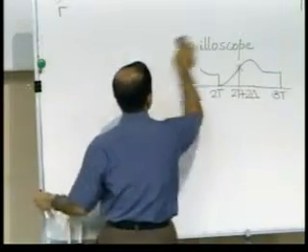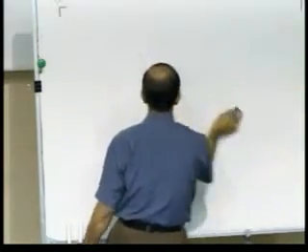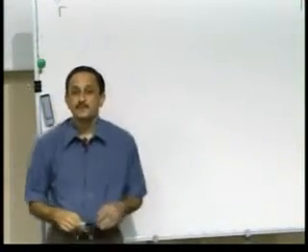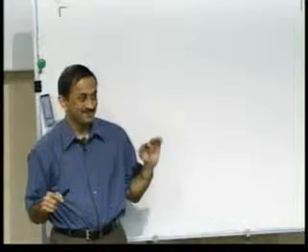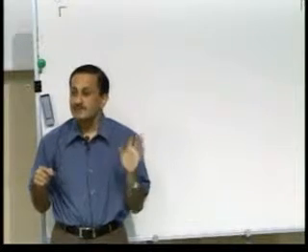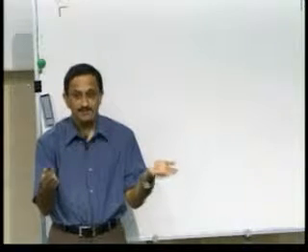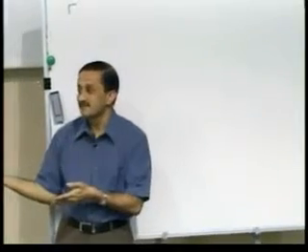You see, one way to interpret aliasing is the following. If we recall, we had talked about modulation earlier, right? We talked about modulation. What did we achieve in the context of modulation? We translated a given waveform, its spectrum, to a frequency different from its original frequency range. That is what modulation did. How did we achieve it? We achieved it by multiplication with a carrier.